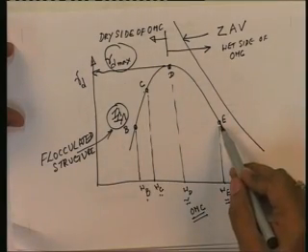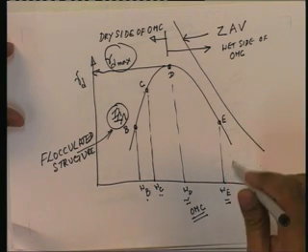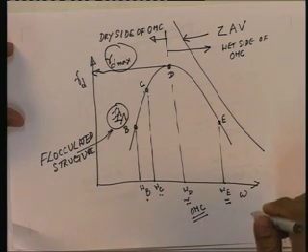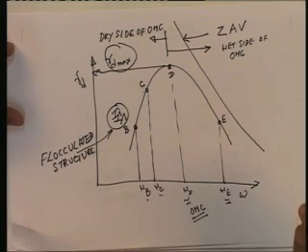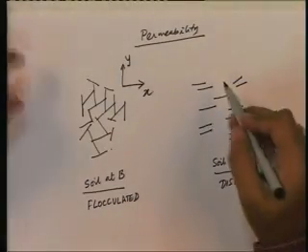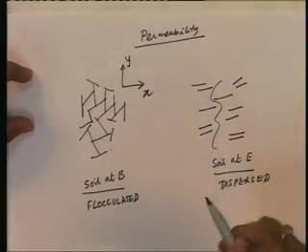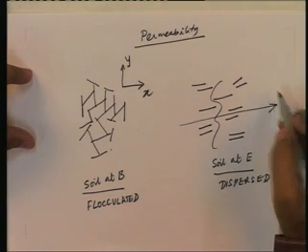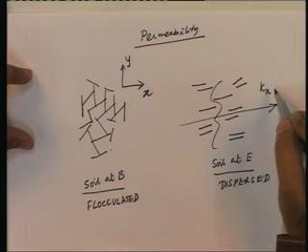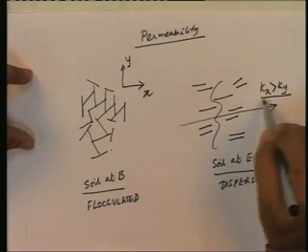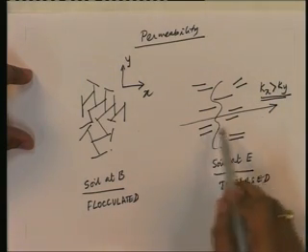Similarly, soil at E, perpendicular to the plane of these platelet particles, the permeability is less. Along the plane of the particles, the permeability is very high. That means that water cannot flow through this easily, but water can flow along the particles. So, in this direction Kx is greater than Ky. So, that is one thing with the dispersed structure.